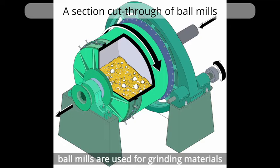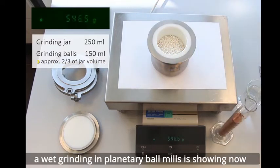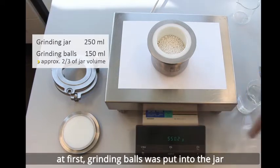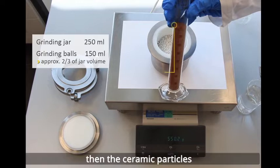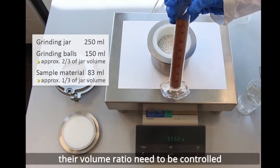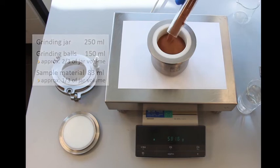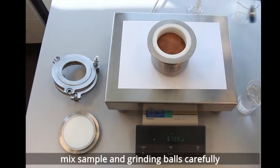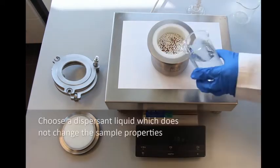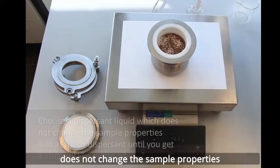Ball mills are used for grinding materials such as ceramic powders. Grinding can be carried out wet or dry. A wet grinding planetary ball mill is shown now. First, grinding balls were put into the jar. Then the ceramic powders were also poured into the jar. Their volume ratio needed to be controlled. Mix the sample and grinding balls carefully. Choose a dispersant liquid which does not change the sample property.